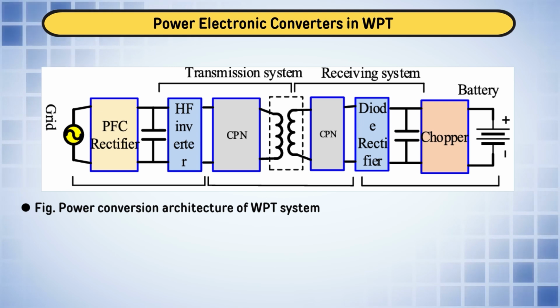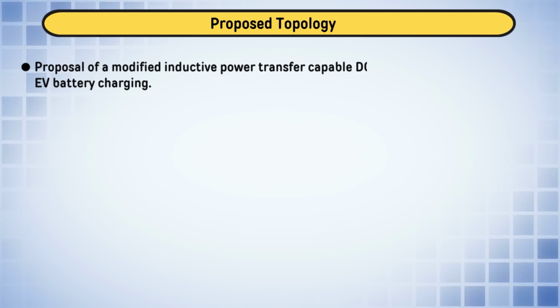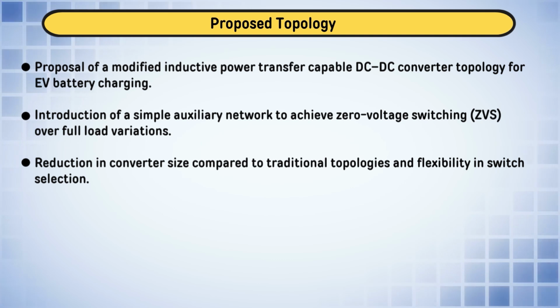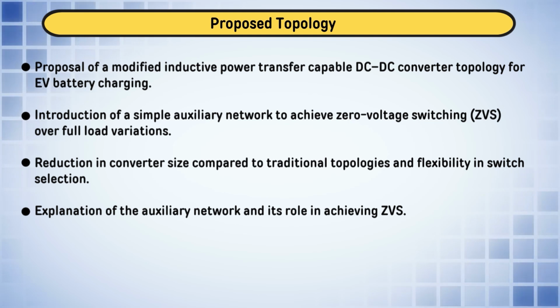We now have a comparison of different isolated DC-DC converters with DAB. This is the comparison table for DAB and other DC-DC converters, and finally, the battery charging through dual active bridge converter control. Here we have sensed the actual battery current and the reference battery current. We have designed the voltage controller and current controller, and depending on the state of charge, the mode selection will be there, either the SOC is hitting the upper limit or the SOC is hitting the lower limit.